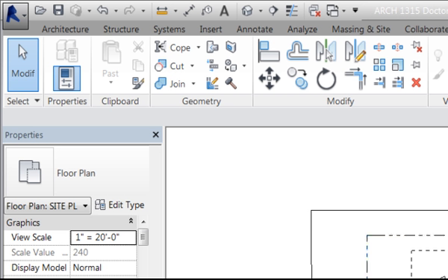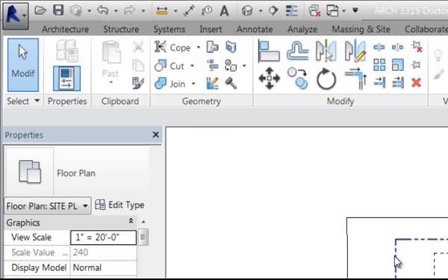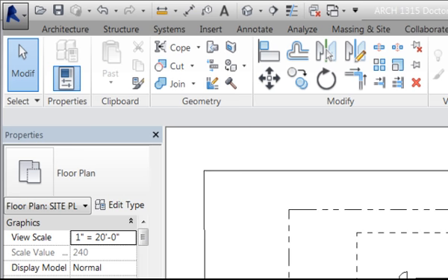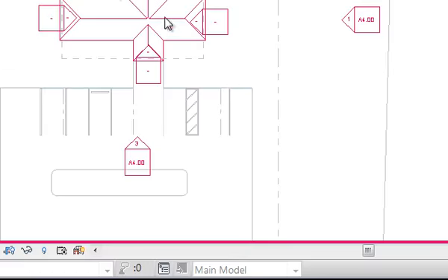Then dimensions. So you need to locate the building on the site, the property lines, major roadways, parking lot items, and sidewalks. And then a fence. You can put a fence up too. Find a fence in Revit and put it in there, or you can just draw a line for a fence. But one thing up at the top, it says a box that is shaded and indicates the building footprint or the overall roof. So you can either keep, remember I had my roof there.